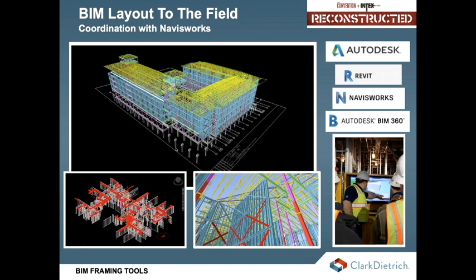So Navisworks, and now it's going to be pushed into Autodesk BIM 360. This allows all that metadata to be brought into one system, and you can virtually fly around it much faster. So that's Navisworks, and that's how you actually see things out in the field. And if you're using a mobile workstation, typically that Autodesk BIM 360 would actually run that system, so you can see the model faster.